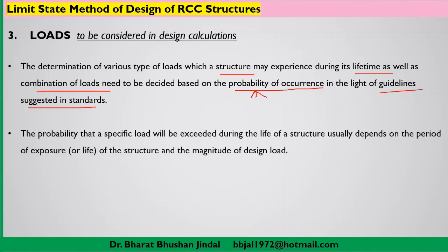The probability that a specific load will be exceeded during the life of a structure usually depends on the period of exposure, that means the life of the structure, whether any type of load can exceed the limits which we have taken into consideration while designing the structure. It depends on the exposure of the structure, how much lifetime you expect for a particular structure when you design it, as well as the magnitude of the design load.